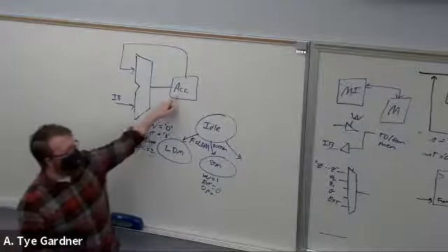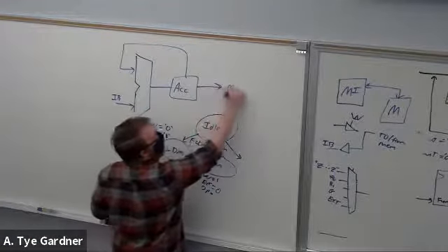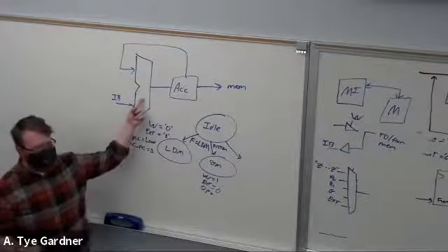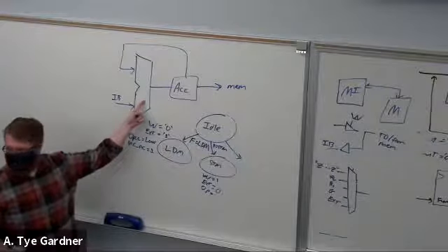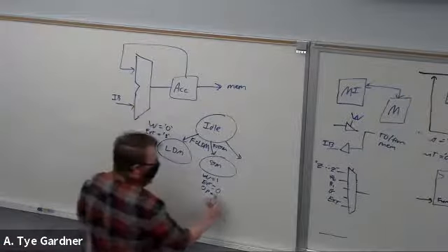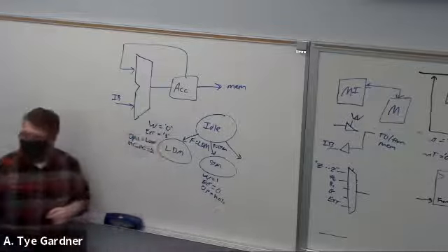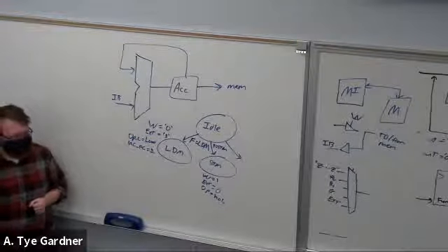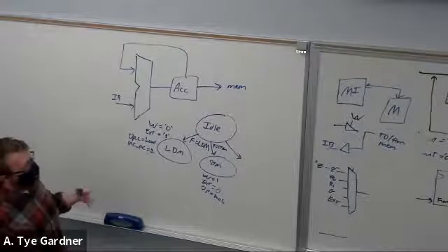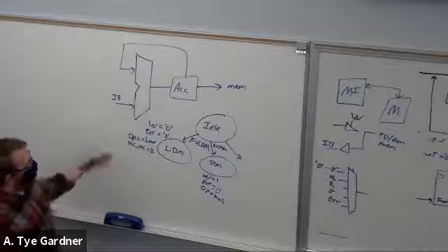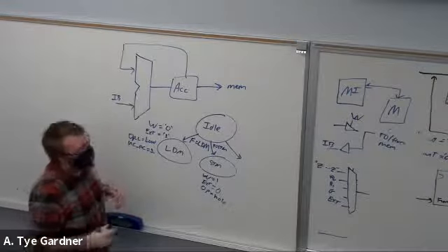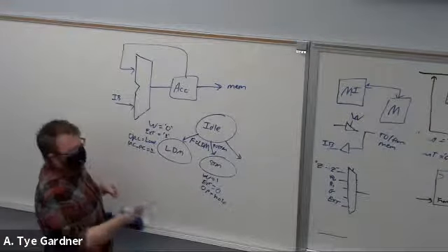If I'm trying to save this accumulator off to memory, what do I do with the ALU? Just hold, don't do anything, right? Keep that value inside of that memory so it has a chance to write it. Okay, so I'm writing to the memory, a clock cycle comes along, ACC updates with itself, it's no problem, and memory updates with the next value.